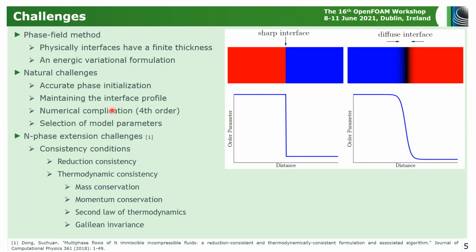Now, there are some natural challenges when using a diffuse interface. For example, you need to accurately initialize your phases. So this is exactly a tangent hyperbolic profile that not only should be accurately initialized, but also should be maintained during the course of your simulation. The other complexity is that you're solving a fourth order partial differential equation. And this partial differential equation contains some model parameters that you don't normally see in the sharp interface methodologies.